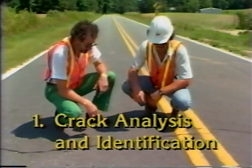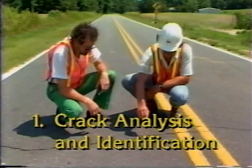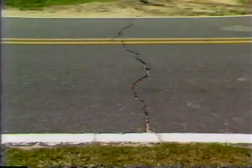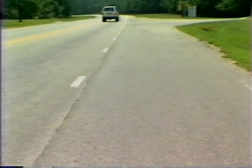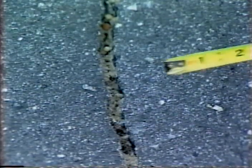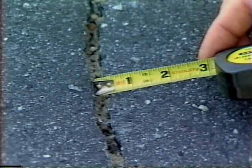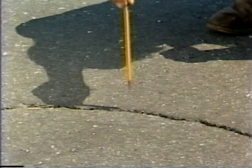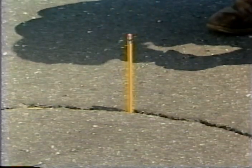Now, let us briefly review the 4 steps of crack sealing. The first step is to perform a crack analysis and identification. This is a review of pavement sections to determine which exhibit the conditions warranting crack sealing. Block or shrinkage cracks, widening joints, and reflective cracks should be sealed. Crack widths of approximately 1/4 inch wide require crack sealing. A rule of thumb: if a pencil will stand up in a crack, it is wide enough to be sealed.